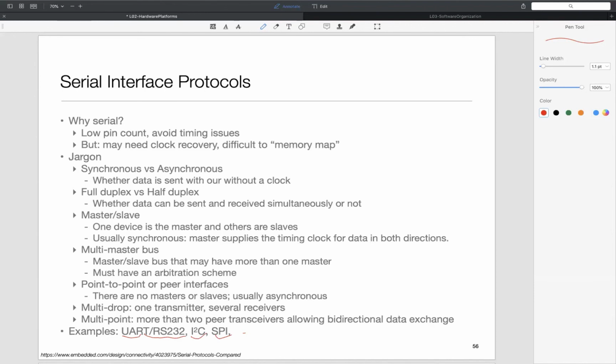Most of our devices have UART, but they typically won't have RS-232. RS-232 is at 12 volts and all, so usually they don't have that. But when you have a proper serial port on a box, then it will be RS-232. These little devices are just UARTs, and there is a way to send UART data over USB. So most of the things you encounter are really UART sent over USB. That is why, for example, your Arduino devices connect to your computer over USB.